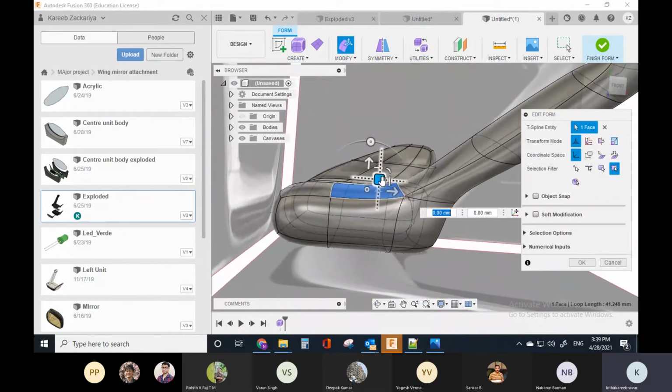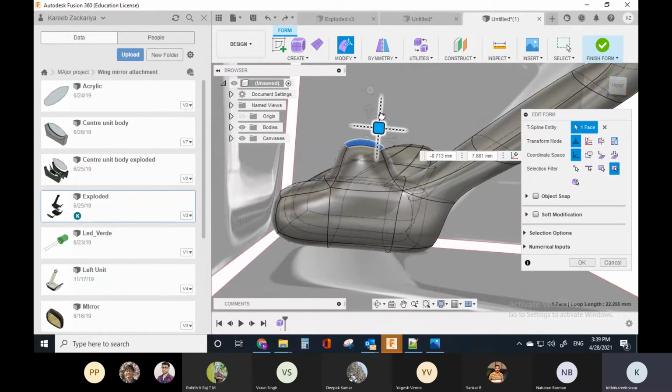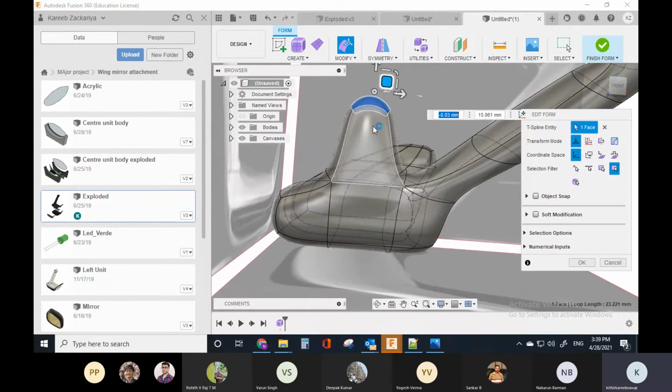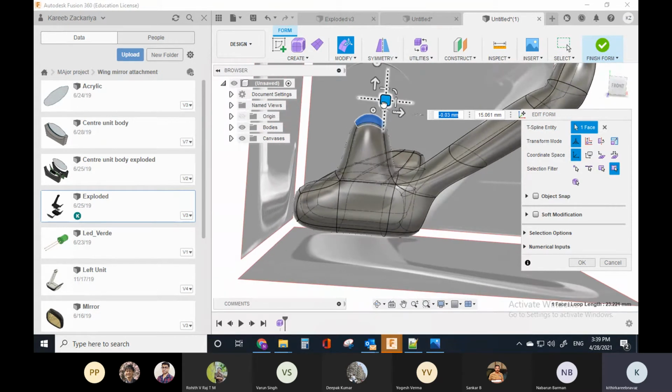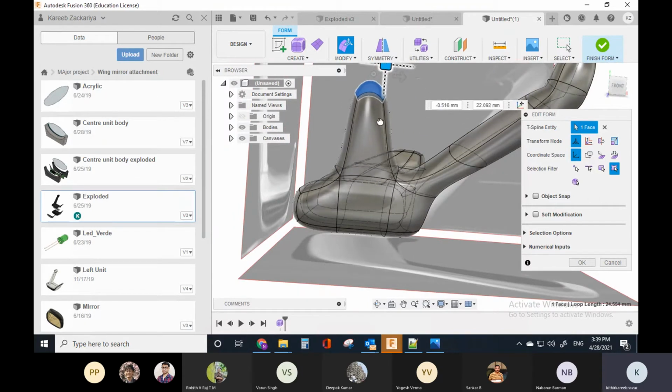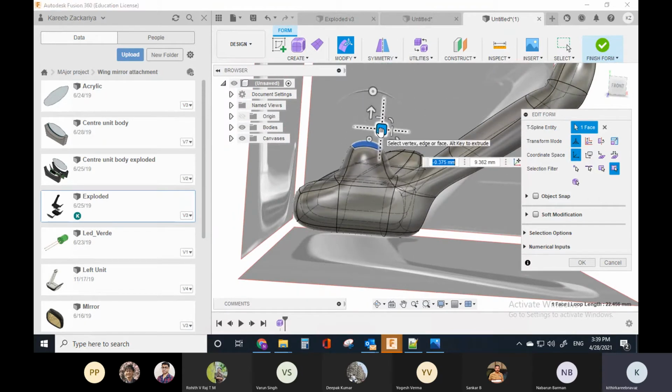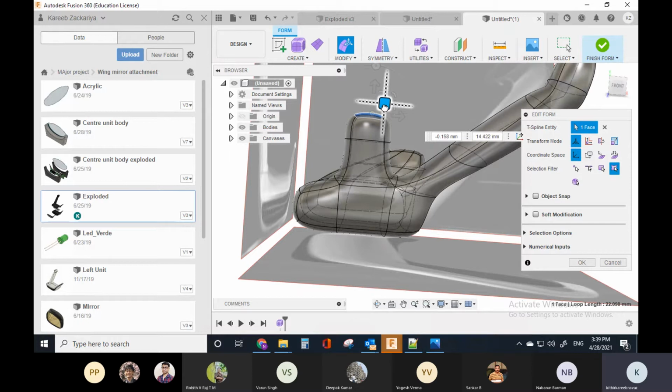If you press Alt and do it, see, it is a new surface that is being pulled. Okay, and there are supporting surfaces that are being created. Now I'm not pressing Alt, I'm just dragging it, so it is moving. Now I'm pressing Alt and doing it, you can see a new surface that is being created, right? This new T-spline curve and these surfaces are being created.